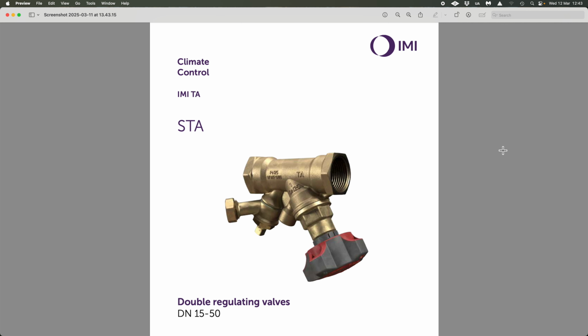Now, what the problem was is that whoever had done the original designs on this block of flats, they were allowing a certain amount of litreage per person per day, and they based their stored water on that basis. Now, what various engineers that were ill-informed have done, they came in and instead of using the existing cold water supplies from the roof space to install a combination boiler, they have thought, well, we have to put it onto the water mains.